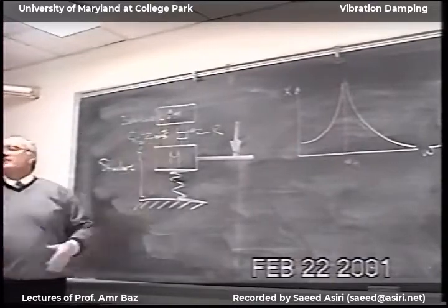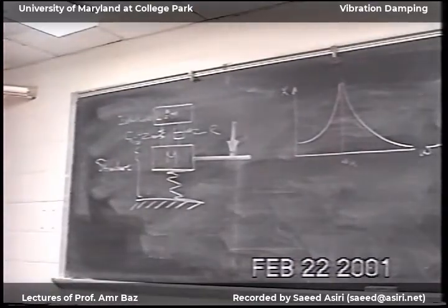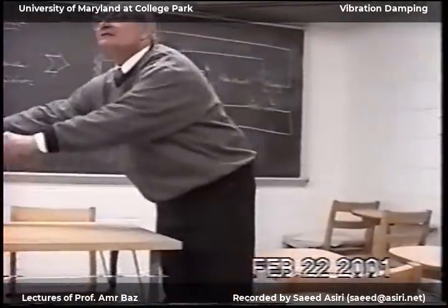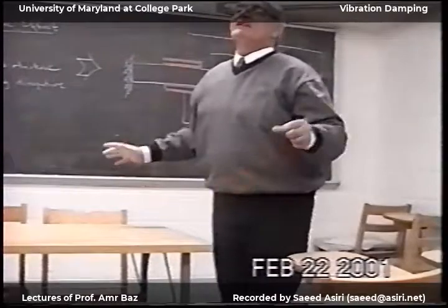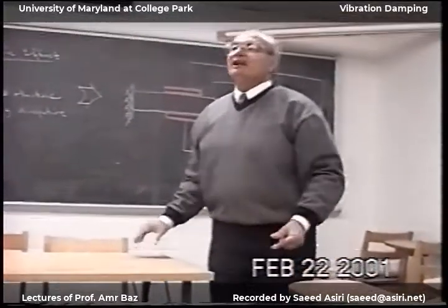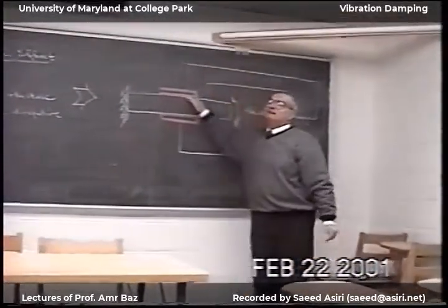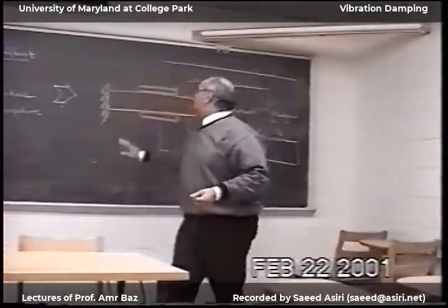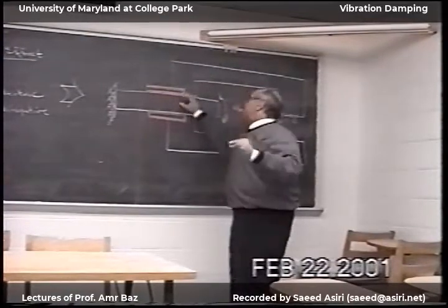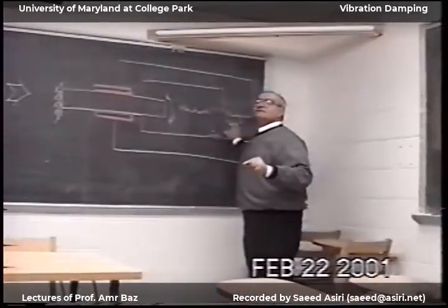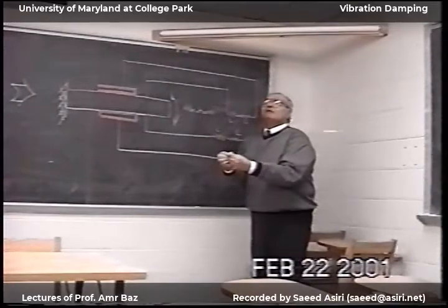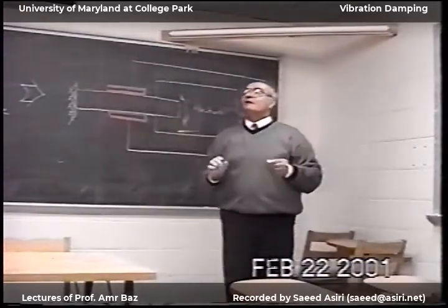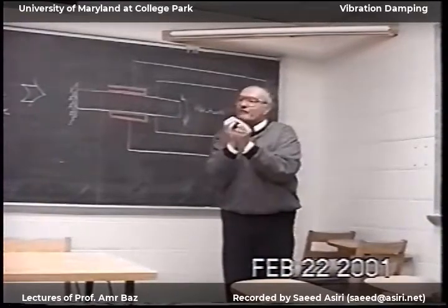If I do this on a very nice table like this, and I want to damp all its vibration, I'll have many masses and springs hanging. And this would be a horrendous design. Okay? Now we have a very nice clean approach. You come, bond this piezoelectric material on it. This piezoelectric material is very thin. And then you can package all these resistances and inductances in a very small place. And then you can damp a very large number of modes of vibration with a very small package.